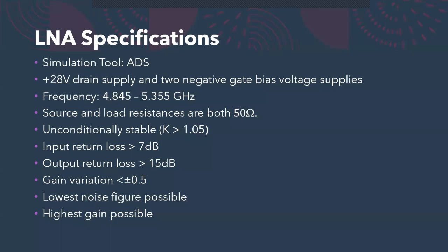Throughout the design, the simulation tool Advanced Design System was used. The frequency band is approximately 4.8 to 5.3 gigahertz. The source and load resistances are both 50 ohms, and the circuit is unconditionally stable, with the stability factor being bigger than 1.05 at all times.